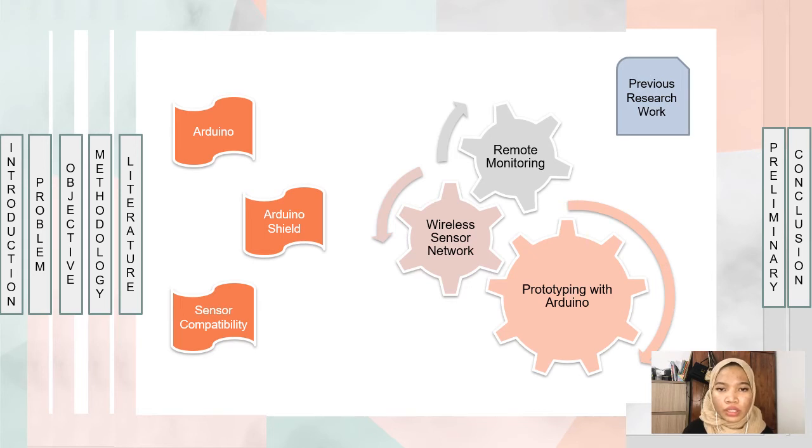The acoustic sensor diagnoses the probable failure by measuring the noises and frequencies emitted by equipment and comparing them to known failure frequencies. Acoustic monitoring tries to prevent failure by constantly monitoring the status of equipment. So I decided to use these two because I would like to monitor the vibration and acoustic present in the engine.